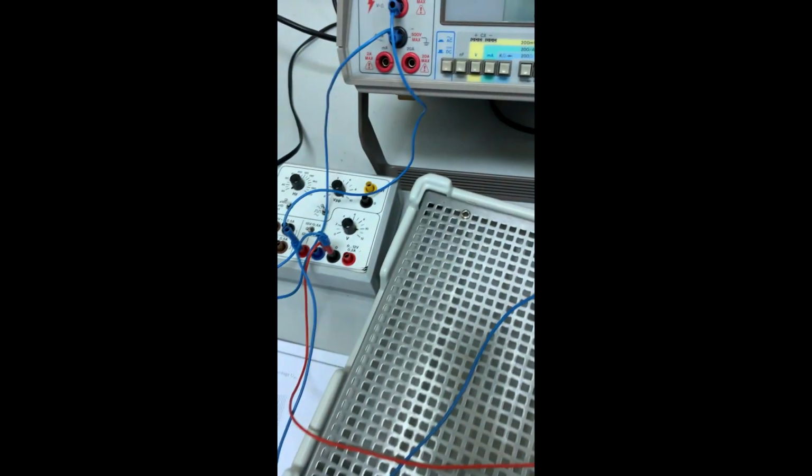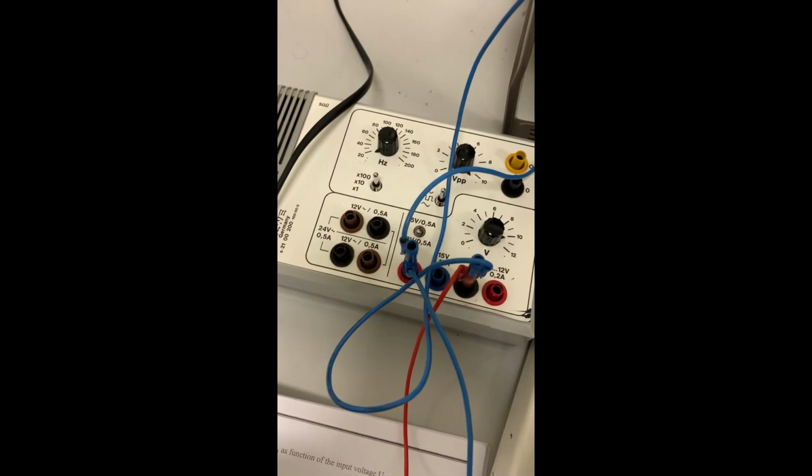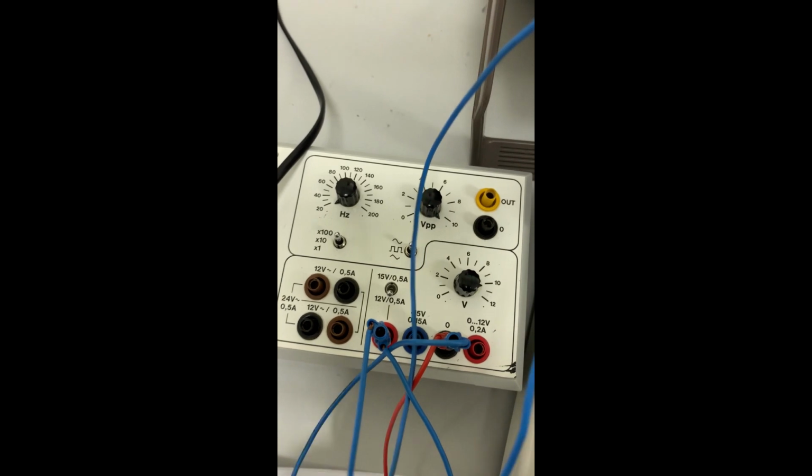Now let us document these values here. For input 3, output is 3. For 4, 4. Up to 6, it is 6. When it is increasing more than the value of 6.2, we see that the voltage stabilizes to 6.2 only. So for this case, you need to connect the supply voltage to the 12 volt fixed supply. Okay, and add the load 2 kilo ohm, 1 kilo ohm, 0.5 kilo ohm, 0.2, 0.1, 0.5